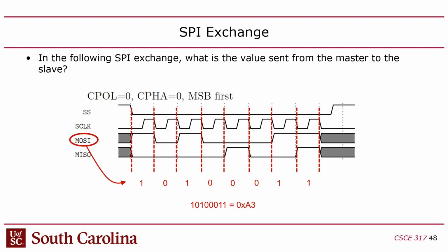Now you might say, well, what does the CPHA and CPOL have to do with the way that you interpreted that? Basically, it was just where I drew the lines, right? But even if I hadn't drawn those lines, you can see there's a pattern, because the data is always stable for 1 cycle, regardless of when it's supposed to be read, right? So CPHA and CPOL are important to understand about what edge the data is being sampled on. But when it comes to just reading the data, you could pretty much just read this in the waveform. You just have to identify these intervals of 1 cycle each.